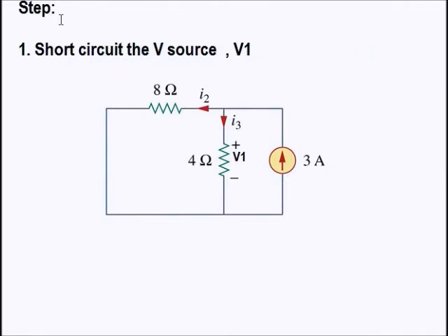For example, if you want to solve the voltage source first, you must make it a short circuit here. Then you can find the value of V1.